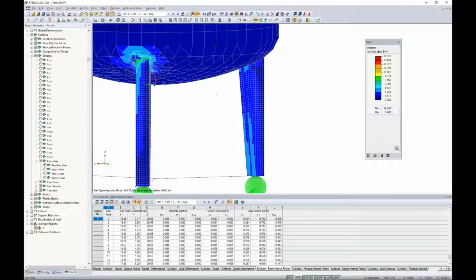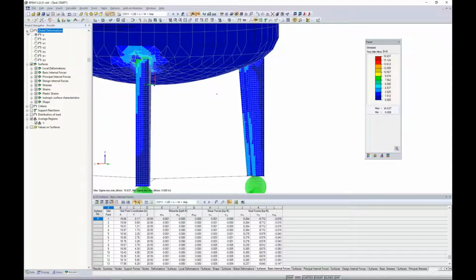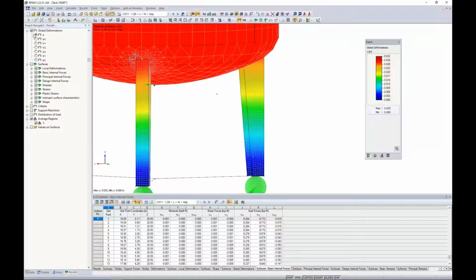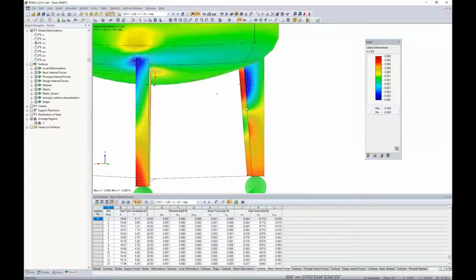So I went ahead and ran this. I'm reviewing our stresses on the structure just like what we've seen before. And in reality, I'm looking at my von Mises stresses. There really isn't much difference here with my leg on the right hand side. But I also didn't really scale that imperfection up too high, only 0.014. So I think it can be concluded that it really doesn't have much impact on the stresses at this location, which isn't necessarily a bad thing. Maybe if we had a thinner material here for our leg elements, we would see more of the results. But in order to make sure that the deformed mesh was applied, I did notice when I turned on my global deformations in the Y direction that we can see that this buckling mode shape with the deformed mesh is considered.